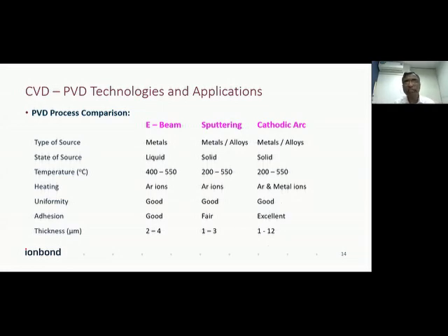Coating thickness is one of the requirements depending on the application. If we see the broaching application, where the tolerances are very low, in the range of say 2 micron, 3 micron, there we need to have a titanium nitride coating of just 1 micron. If we give 3 micron, 5 micron, 10 micron, then instead of cutting, we will observe rubbing, and there is no component manufacturing over there.